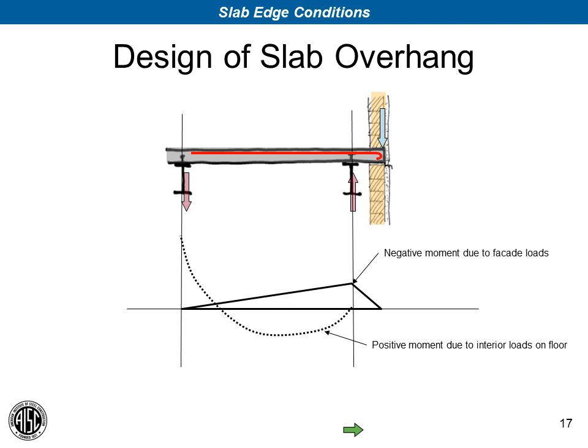Now, when you look at this as a beam, don't forget that the cantilever action creates a significant amount of negative bending moment over the spandrel beam here. And so unlike when we typically design slab on deck as a simple span between adjacent beams, in which case you concentrate on the flexural capacity as a function of the reinforcement, in other words, the deck at the bottom of the beam. Here you need top reinforcement in the slab to address the negative moment due to the facade loads. And looking down below, you see the moment diagrams for this condition.